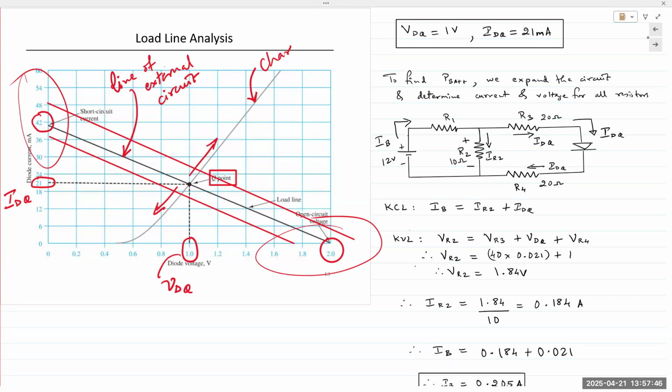Okay. So again, if we want our diode to operate at say 1.2 volts, let's reverse engineer, right? Because as an engineer, that's what you'll be doing. You have a goal in front of you. You have to reverse engineer and go to the beginning. So if you want your device to operate at 1.2 volts, you can find the intersection point somewhere right here. So you have VD, you have ID. Now determine what voltage value would be required from the battery, from the original supply. Does that make sense to everyone?